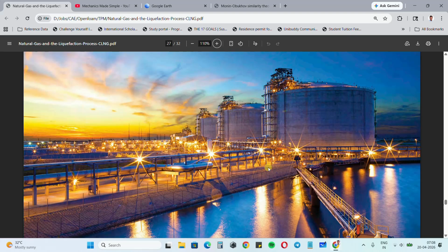Rather than working with a neutral atmospheric boundary layer, we will be working with a stratified atmospheric boundary layer, and also instead of working with model scale geometry, we will be working with a real scale geometry. And to cope with that, we have to follow concepts of roughness scaling rather than viscous scaling based on y plus. And I have organized the video like this.